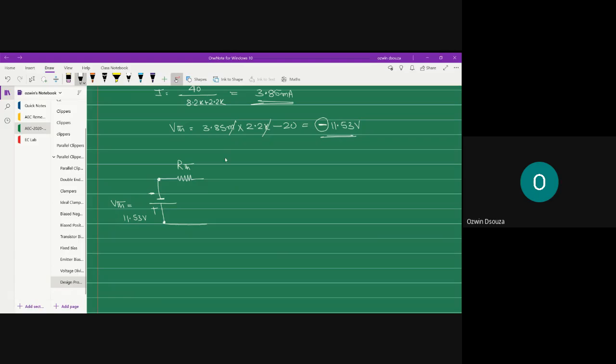And this Thevenin's network, I'm going to connect to the load, right? What is my load? Load is nothing but the transistor circuit. So whatever you had removed while finding out VTH and RTH, you're supposed to insert back. So that's your emitter resistor, it is connected to RE.